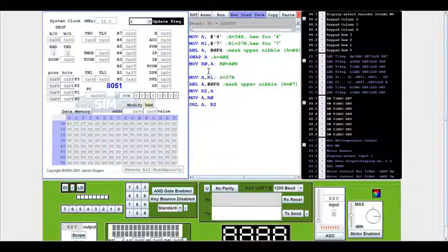Okay, so again I want to do the same thing with the 7, and I can do it only using the accumulator. So that was the problem in the earlier PDF. So for that, I'm just going to store this 40 in a particular register. I'm moving it to R0, keeping it safe there, and then taking 37 and operating on that. Again I'm masking, so I'm getting 07 here, and that 07 I'm moving to some other register, R2.